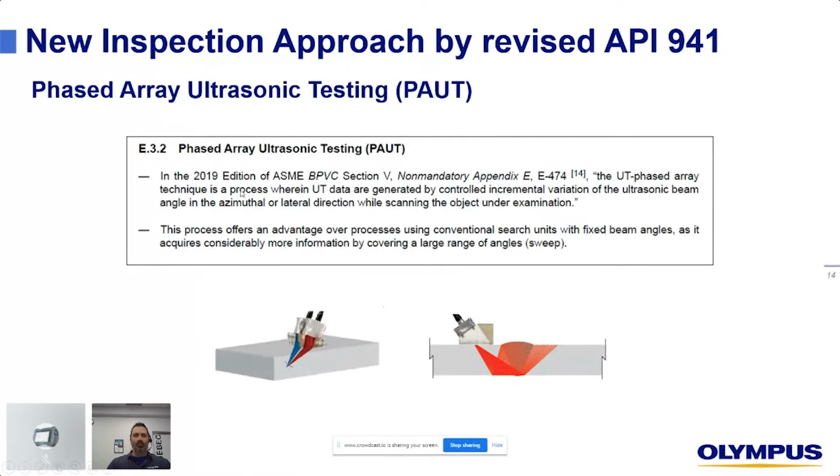Phased array ultrasound. What is phased array? What's the advantage of phased array? What it offers over conventional UT is that from a fixed position, you can have multiple angles covering a wider area. You can also combine different element input to focus at different depths, given that we are working in the near field.